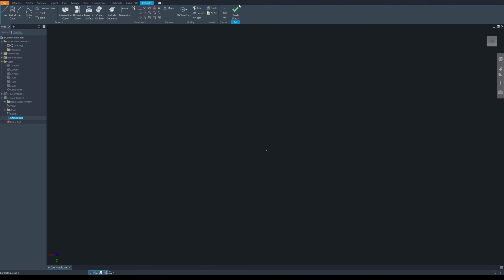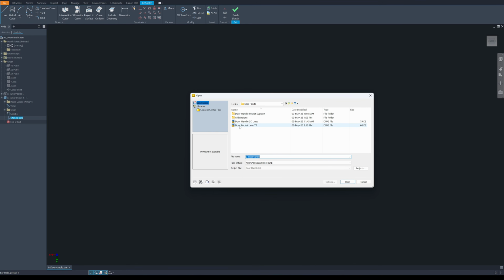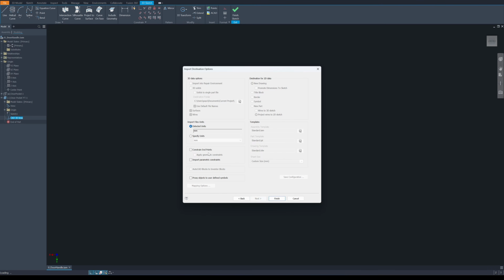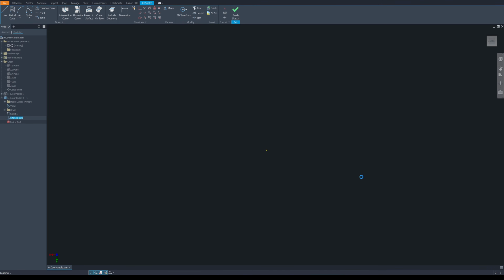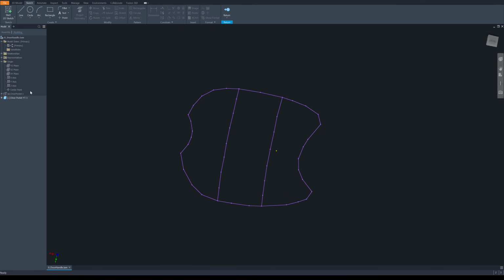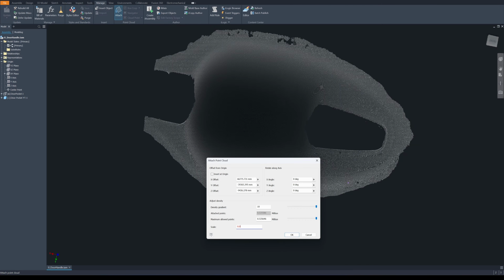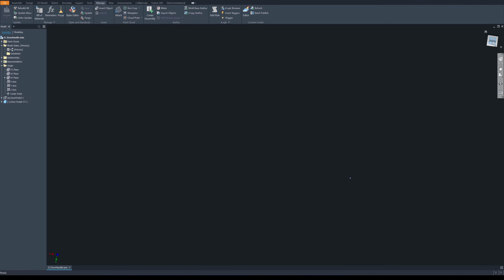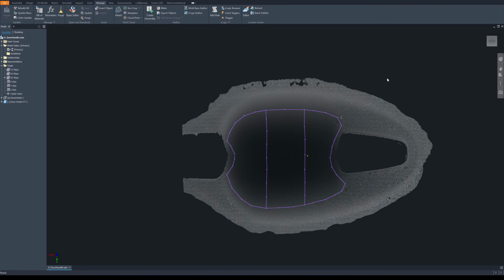that we made from AutoCAD. Click on AutoCAD, click on the line that we just created. I'm going to import the lines. The unit is in millimeter, so it's correct units. Okay, now we have our 3D lines ready for creating a surface. Okay, before that, let's import the point cloud. Manage, attach 0.001 for the scale, and insert at origin. So it should be in the same position.